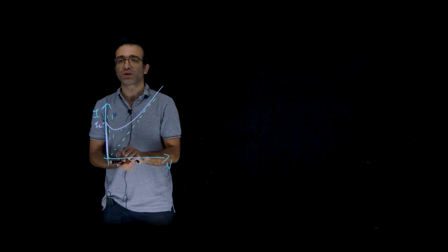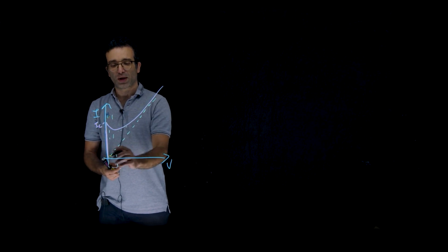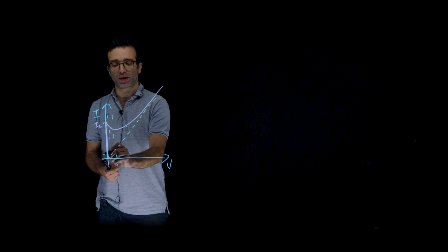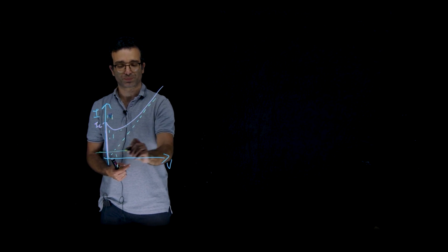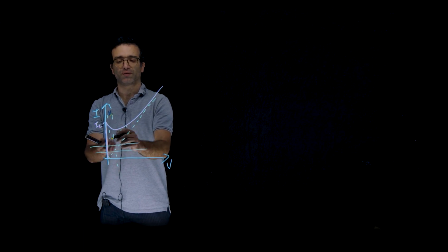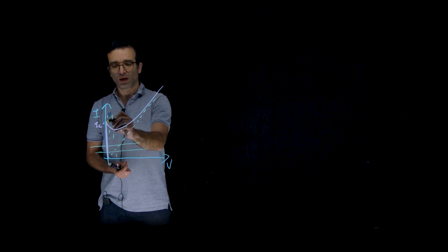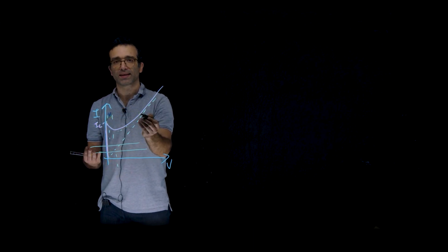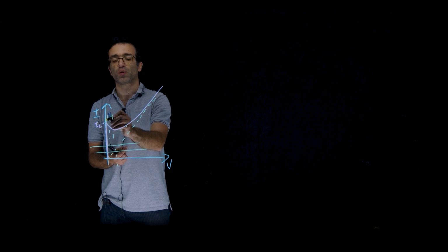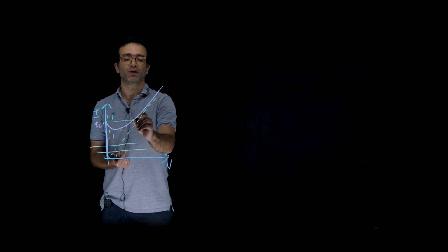Now, let's assume I would do the opposite. Let's assume that I would impose the current and measure a voltage. Now, I don't have a problem in the zero voltage state. So I impose, let's say, this current, and I get 0 volts. I impose a larger current, everything is fine. The problem arises when I'm here. Here, if I want to raise the current a little more, I can't without staying at 0 voltage. The only way I can raise the current is by increasing the voltage significantly, meaning I'm jumping to this point.